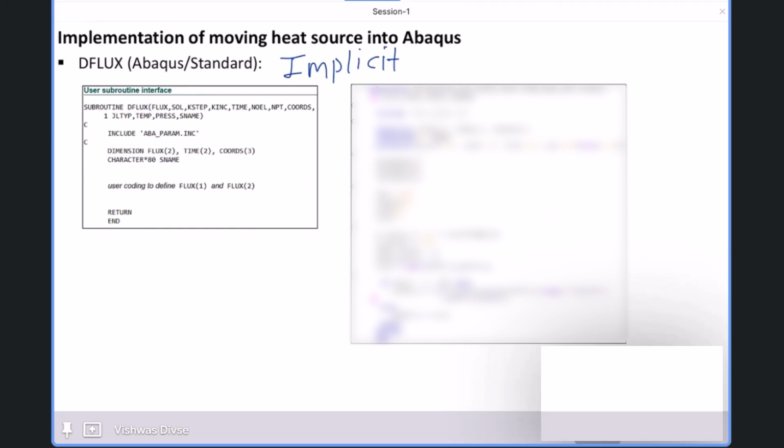whenever a model or simulation consists of a lot of non-linearities, dynamic phenomena, contacts, damage, such kinds of complex things, it's very difficult to handle with the implicit algorithm. And mostly such very fast wave propagation phenomena involving material non-linearity and contact non-linearity, engineers and scientists prefer the explicit method because that will converge your solution.